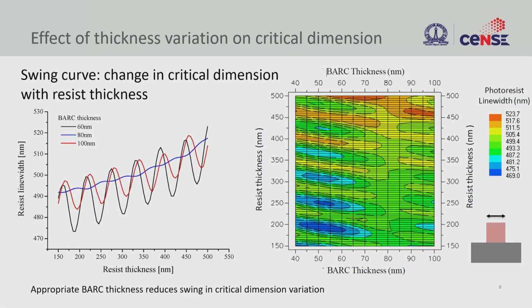Okay. So we looked at the photoresist thickness, and then we saw this standing wave, right. So the standing wave pattern would result in a certain CD or certain dimension, and based on the thickness of your photoresist, the standing wave wavelength or pitch will also change. Okay.